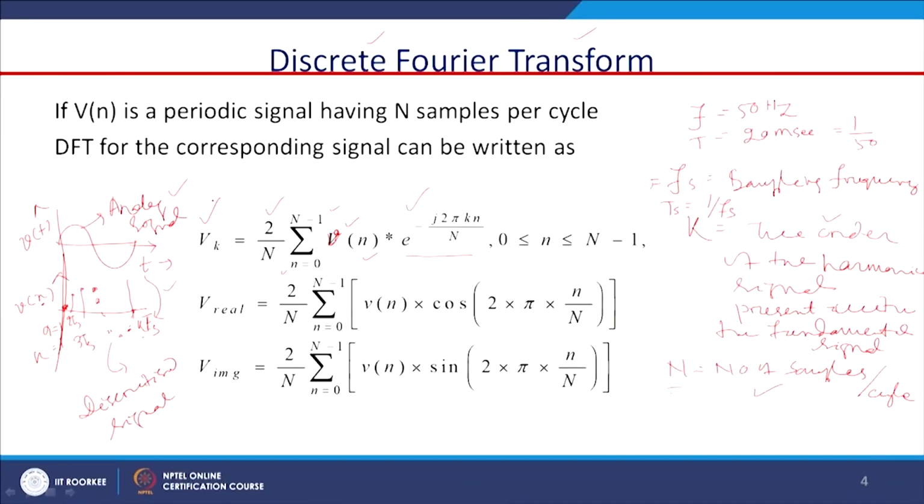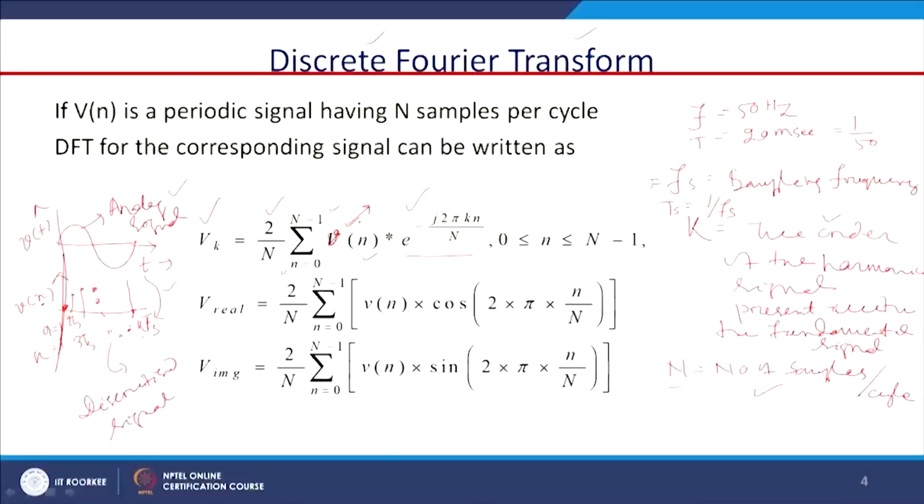Phasors mean the frequency domain is a must. We should know at what frequency we are going to calculate the RMS value of the signal and the phase angle of the signal. So, this is our discretized time domain signal, and we are converting it to the frequency domain signal for calculating the magnitude and phase angle.